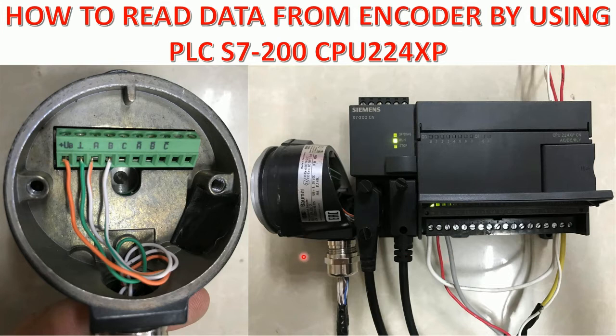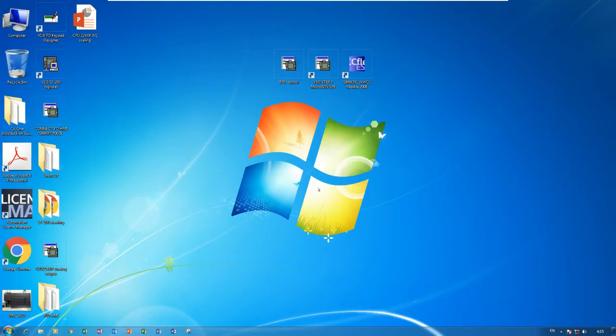So let's go to set up the parameters, or we can say the wizard, for the high-speed counter to read data from the encoder to the PLC. Here I will use STEP 7 MicroWin version 4 SP9 and WinCC Flexible to create a new project to show the value of the encoder on the HMI also.